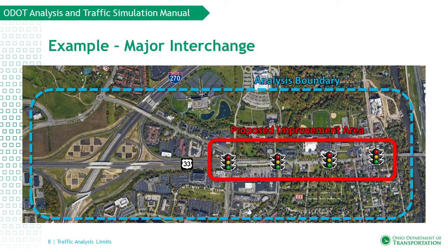Lane utilizations, especially to and from the westernmost study intersection, are likely affected by the interchange configuration. Therefore, these effects should be modeled in the analysis. Furthermore, this interchange should be included in the analysis to ensure that improvements at the signalized intersection do not back up and adversely affect the interchange and interstate.